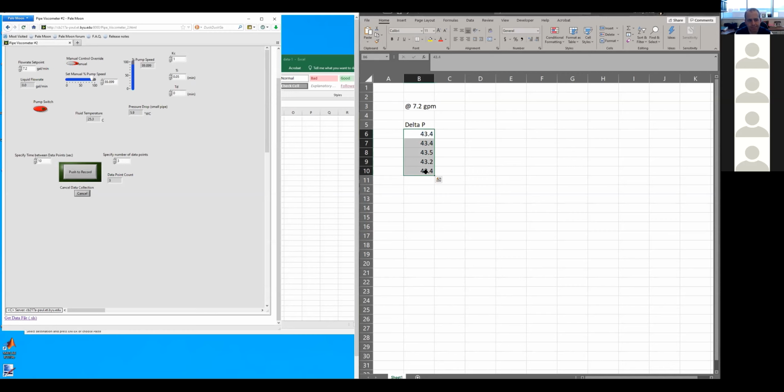Any ideas? Would the flow in the system be consistently turbulent or laminar? Would it be consistent enough that you'd have an identical delta P? Because the deviations are pretty small in terms of the overall pressure drop, so it could just be little minor fluctuations.